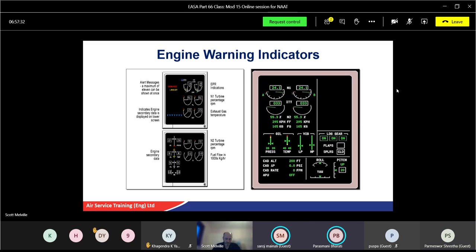Control thermostat. Thermostat opens. Yeah, good. And then what happens? The valve modulates towards the closed position. Yeah, good. And reduce the load and ends. Yeah, and reduces the fuel supply. Yeah, good. If it doesn't, though, it gets to 695 degrees, what happens then?